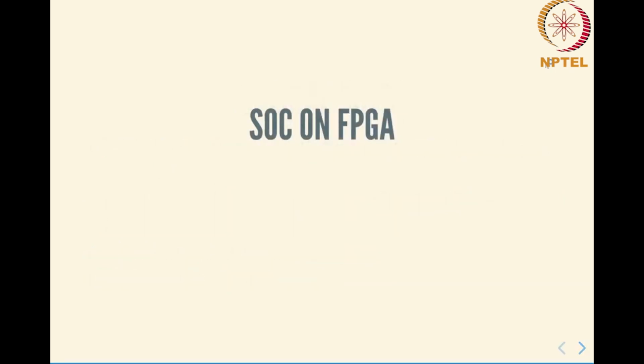So putting it all together, we can now think of a complete system on chip that can be implemented on an FPGA. The control logic of the CPU can be implemented with the lookup tables and flip-flops, because after all, it's some kind of a state machine, while the block RAMs can be used for storage, either for the register files or more likely for caches or local memory.